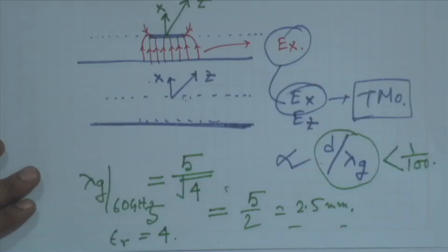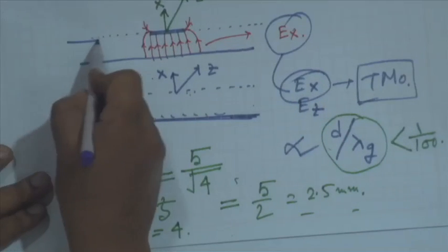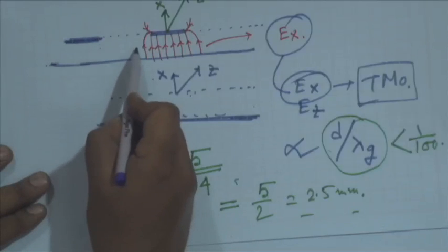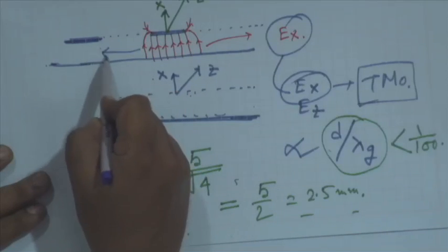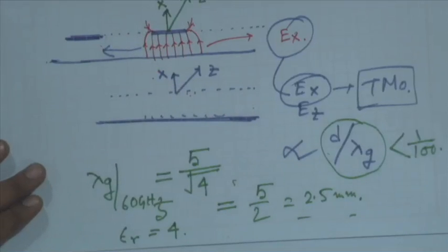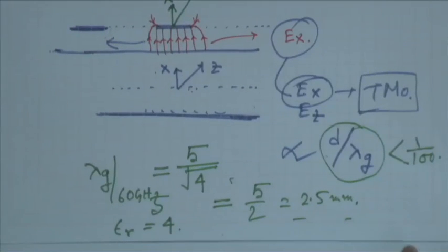So, if I have one more microstrip line here carrying, let us say, another signal, we will have coupling through the surface wave. This is not just by the fringing fields. So, at millimeter wave frequencies we typically face this problem, the detrimental effect of TM0 mode, particularly for microstrip line.